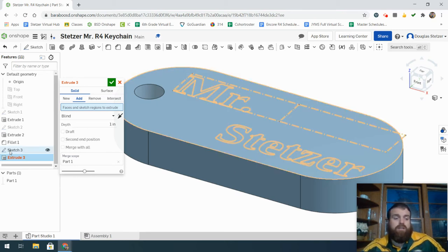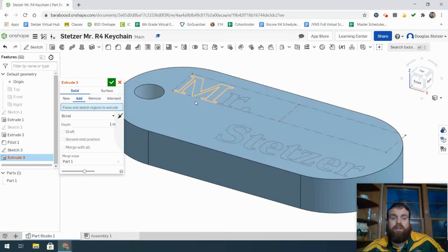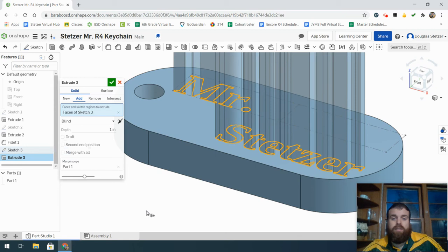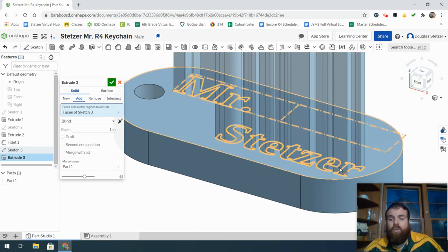That's okay. The other thing I can do, and the easiest way to do this, is to just select your sketch as a whole. We can select it on our image, or we can select it in the tree itself. If I select my entire feature, it should pop through. If it does not select some of your features, you may need to go in and edit your text to be a different font, because some of those entities may have openings. They might have a hole in part of the letter that is invisible to us, but the program can zoom in far enough to see that.